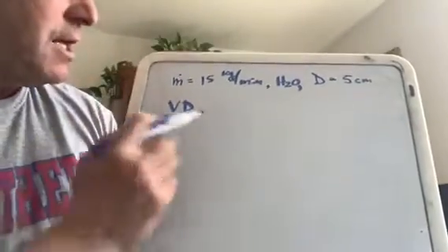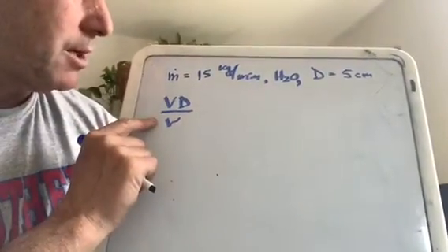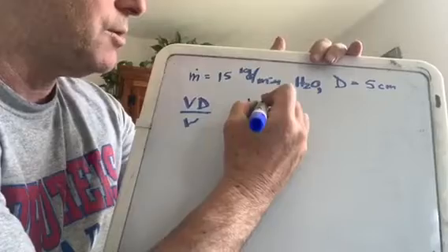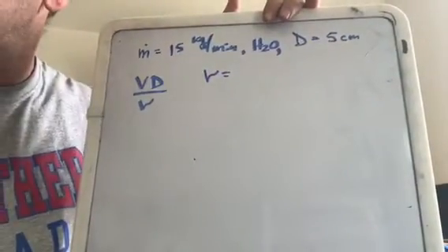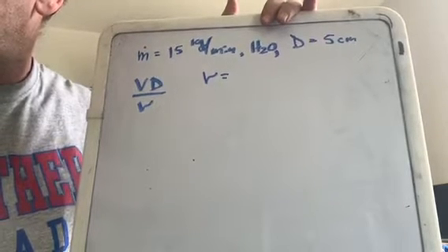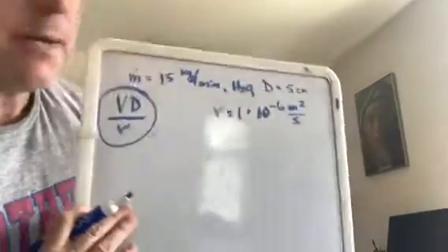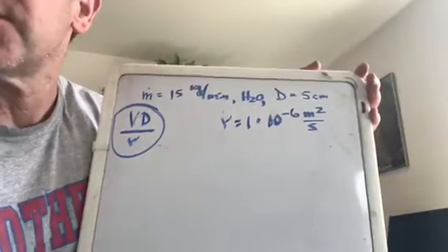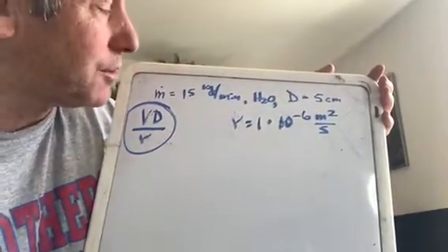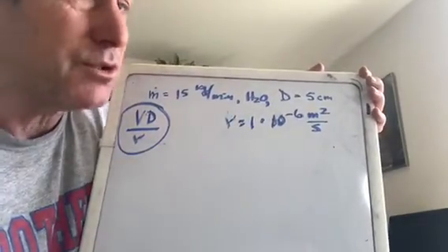But to finish things off, if we had the information like this, how about calculating the Reynolds number using this formula right here? Well, D we got, so that's easy enough. Kinematic viscosity: once again, we would go to our tables, and I'm going to try to use the same line there, 295 K. Actually, I'm sorry, the heat transfer book doesn't give kinematic viscosities in their tables. But there are many tables that have it because it's such a useful parameter. So here's a good approximation of the kinematic viscosity of water: 1 times 10 to the negative 6 meters squared per second.